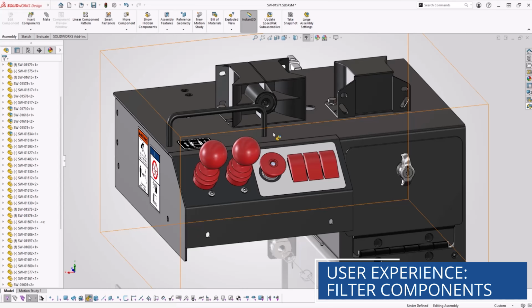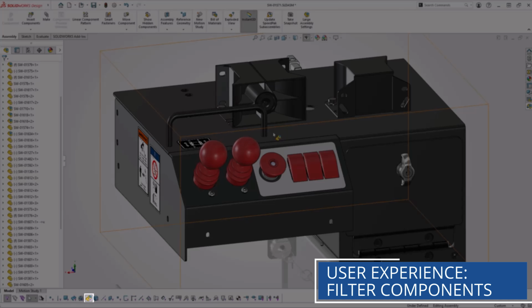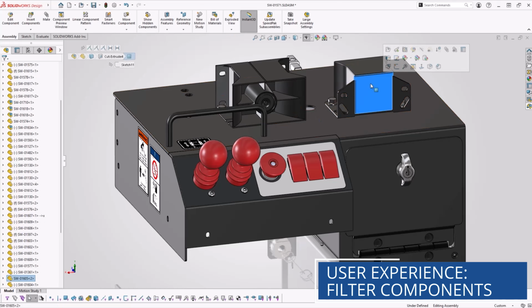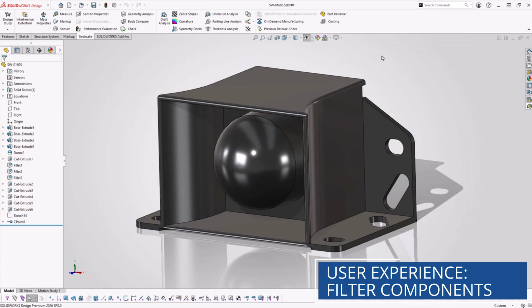In the past, we would either have to find the sub-assembly in the Feature Manager design tree or use the D key to drill down to what we want using breadcrumbs. Tapping F6 on the keyboard will keep the selection filters toolbar present, but turn all filters off. We'll now left-click the forward-facing loudspeaker and open it using the context-sensitive toolbar.